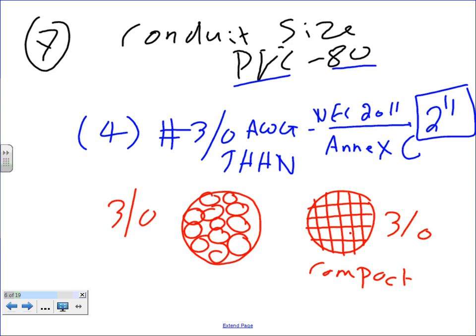So you have a 3-inch conduit, and you want to move from, say, 1/0 to 4/0. But if you are to move to 4/0, you're going to get a bigger conduit. Then you use compact conductors. They can fit in a smaller conduit size. Good point. Any questions, guys?